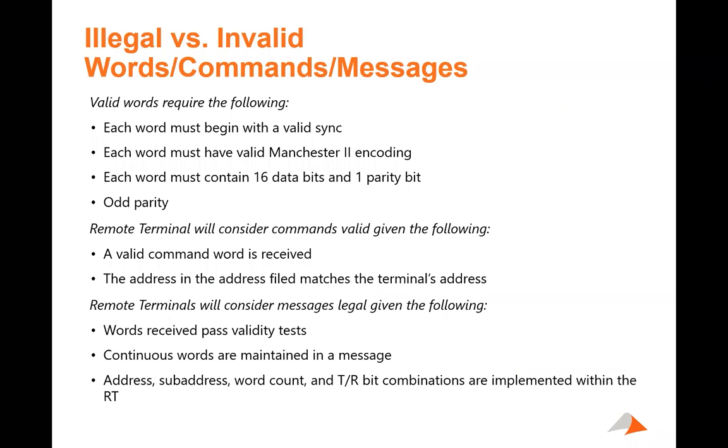You've heard the terminology when I refer to illegal versus invalid. Illegal means it just doesn't work. It doesn't belong on the bus. There's something fundamentally wrong with the form of the waveform, typically, or the RT address. Valid words require that each word must begin with a valid sync, so it's got to be 1.5 times up, 1.5 times low, or vice versa for data words.